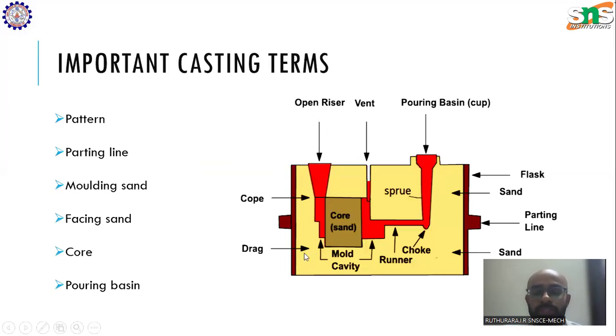And how will we know if the metal is filled or not inside the mold cavity? Here comes the purpose of riser. Once the metal is completely filled inside the mold cavity, it will rise through this riser. So we can predict that the entire mold cavity is filled.